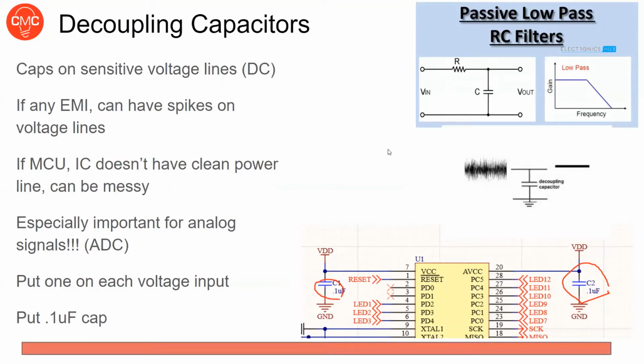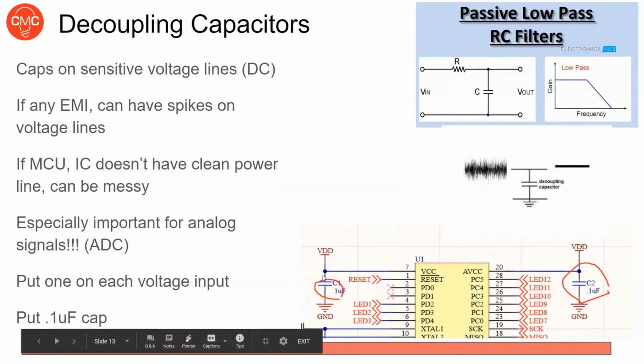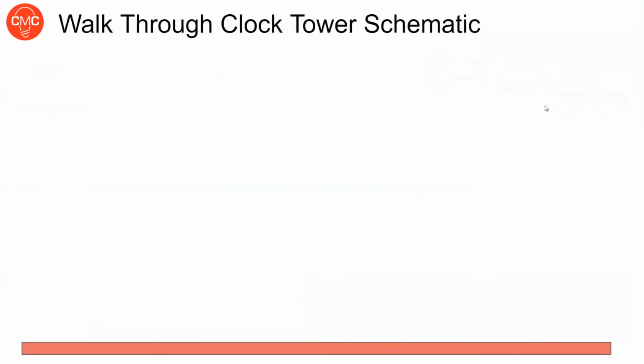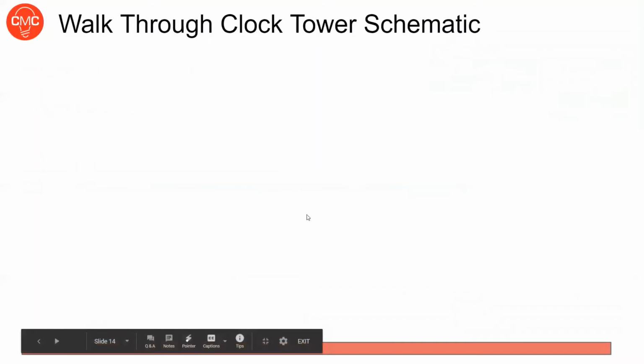a transformation like that, if you turn a source on, that's basically just a big spike, because it's going from 0 to VDD really quickly. So if you flip a switch, it's going to create basically a high-frequency signal, and you don't want that to be really slow to rise if you have too big of a capacitor. So we use 0.1 microfarad capacitors. You'll see this on literally every schematic you look at. You'll see 0.1 microfarad capacitors. That's why.